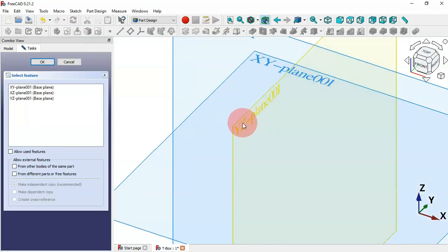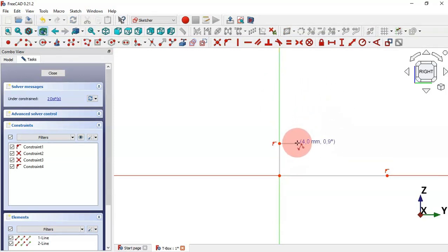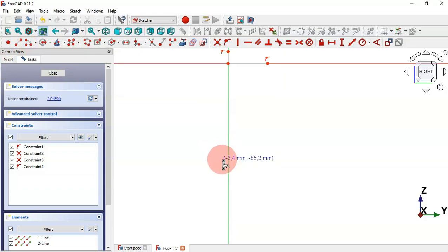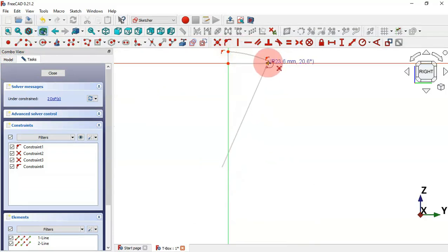Let's select this YZ plane here. Okay, and now we go to sketch adjustments, and we need to select the polyline tool, this tool, and then we click in this horizontal axis and then this origin point, and also we draw this vertical line here. And now let's select arc tool. Okay, zoom out, and now let's connect these two endpoints here.